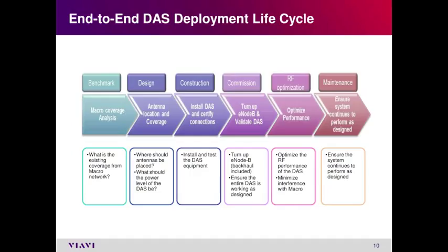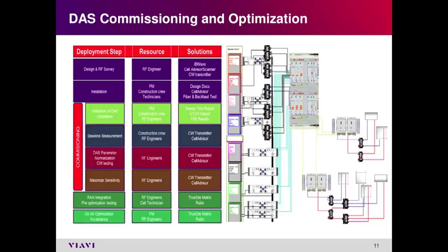user experience. In another way, if you look at the stages, on the right-hand side I've just shown you an example of a 2-operator DAS design sheet that came out once you created it. So basically, you are taking the RF from the radio link, sending it to the conditioning equipment, then to the DAS head end, and then to the remote radios and to the antennas. You can see a lot of splitters and connectors in the middle, and you have to manage the path loss and the link losses. You have to understand, am I within my specs that were put in the link budget?